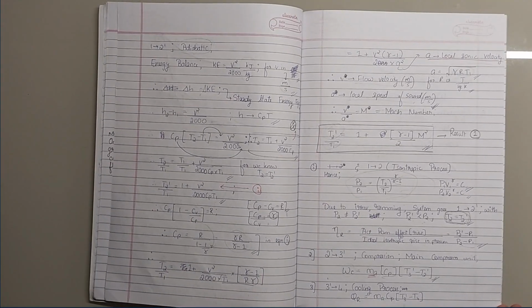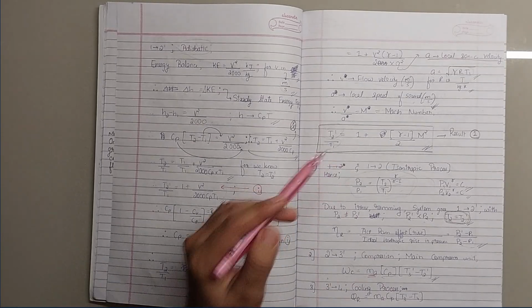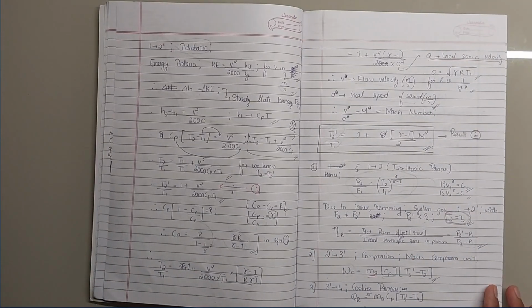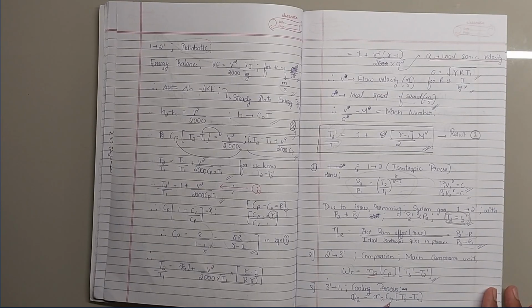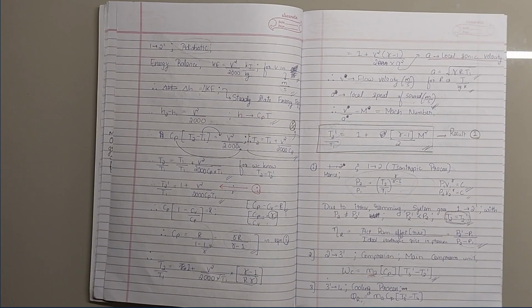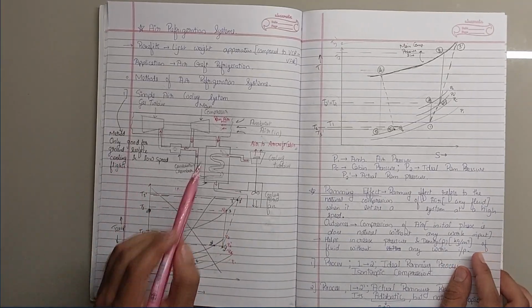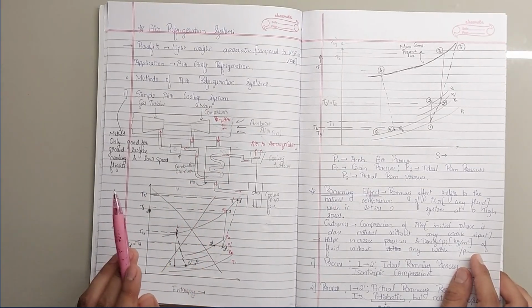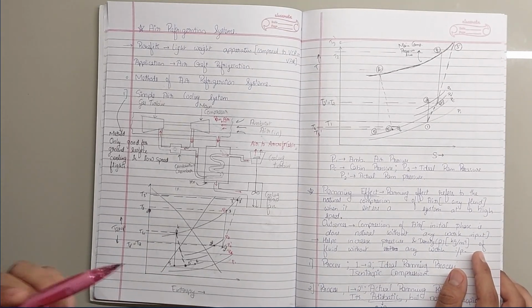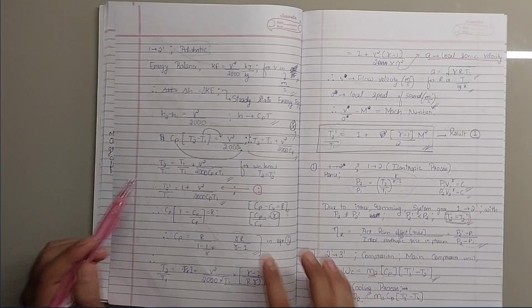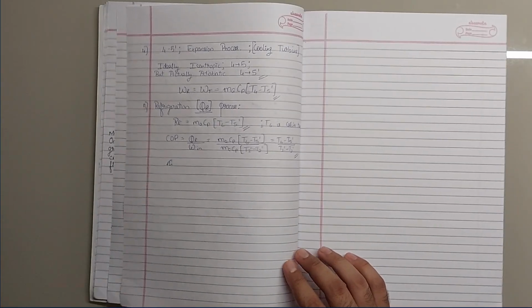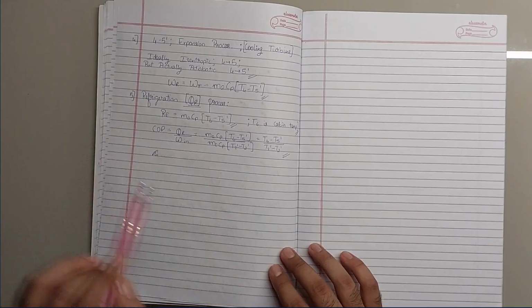Now we'll go for the cooling process. The cooling process takes place from 3 dash to 4. Herein the cooling takes place, QR equals MA CP into (T3 dash minus T4). This cooling process is not the refrigeration effect. It is just a part of the heat exchanger. It is not the QR. It is just a cooling process to cool down the air which is still in the system. The refrigeration effect only takes place when it gets out into the airplane cabin.